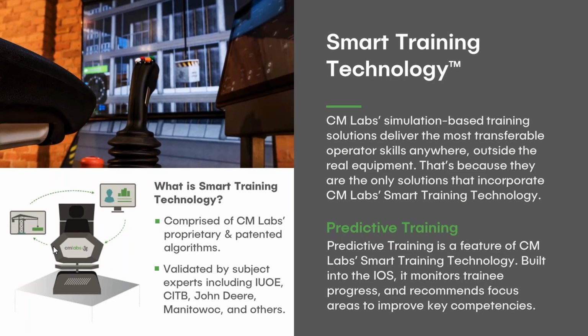So we simulate engines, and that engine is connected to a governor, or that engine is connected to a hydraulic pump, a variable displacement pump. We simulate that, and we simulate the hydraulic pump that has a rod side and a head side, and we simulate the safety valve. And what we do is we piece all those little tiny pieces together and have emergent technology come out of that. And then we tune it, and we tune it, and we work with real operators so that the equipment becomes the sum of individual parts, hopefully feeling like the real equipment.